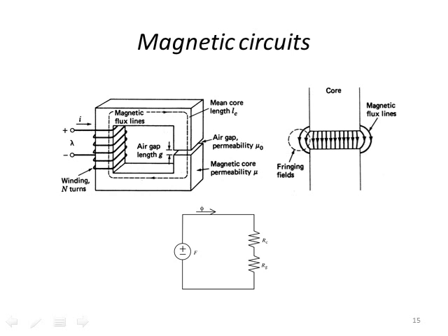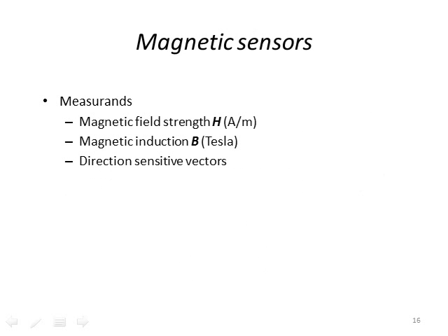And then if we have an air gap, then we can also include this into our calculation, so we can then make a lumped circuit that consists of a reluctance for the core and then a reluctance for the air gap. And remember the permeability in the air gap, then we assume just mu sub 0, the permeability of free space.